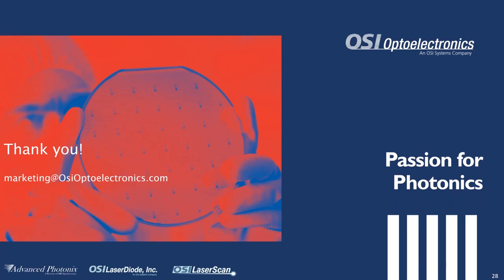Many scientists and engineers are working on improving IR sensitivity of silicon, for example, silicon APD, to allow high gain at wavelengths above 1000 nanometers. And unfortunately, up to now, the best way to do it is still to increase the thickness of silicon, which will require, of course, applying high reverse bias. So that's the only feasible and most practical way for now.